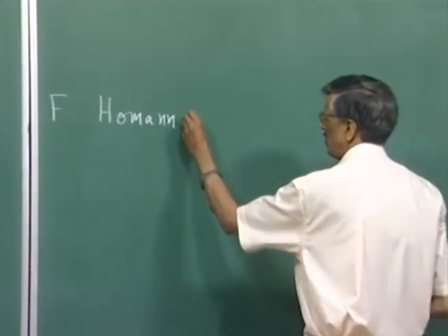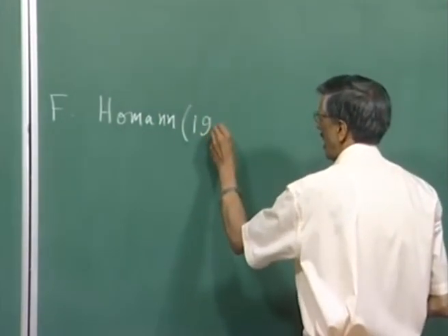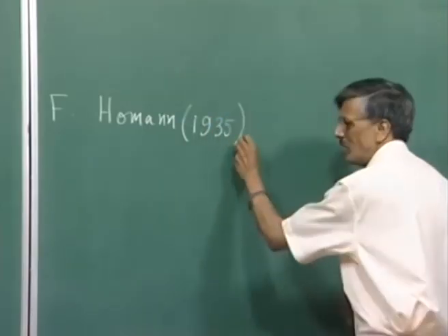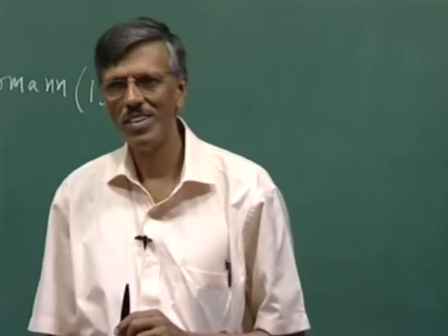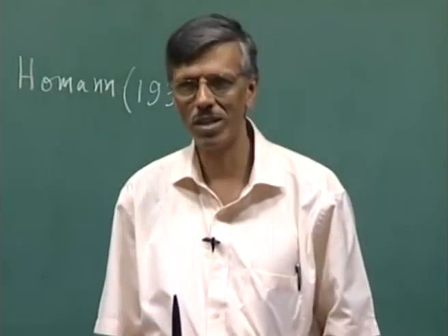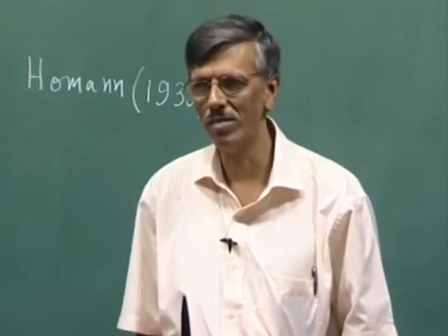I think it is 1935 or so. I do not exactly remember. I can give you the reference. He actually set up a very interesting tunnel. Instead of using a wind tunnel or a water tunnel, he constructed a small tunnel which worked on a highly viscous fluid, a liquid, almost like your lubricating oil, with a very high coefficient of viscosity. And then he put the cylinder, and he did not see vortex shedding till the Reynolds number was 65.